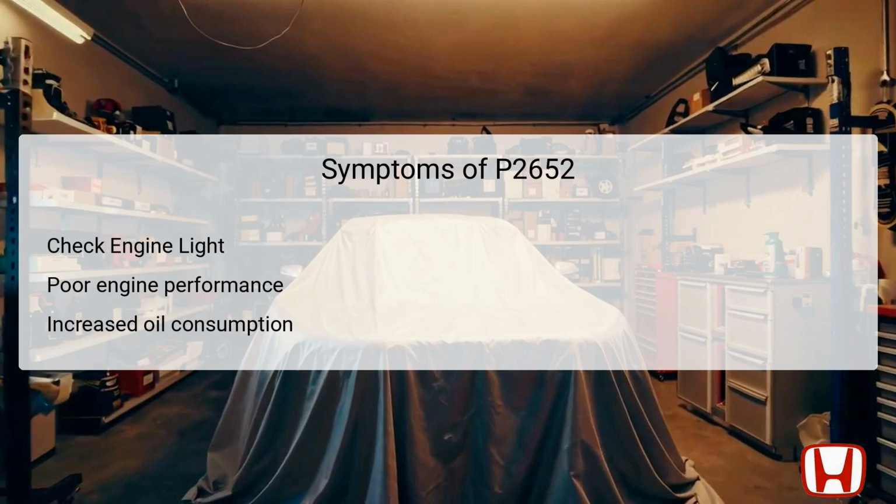Furthermore, abnormal engine noises, such as knocking or ticking, can occur as a result of insufficient oil supply to the rocker arms. These symptoms together highlight the need for immediate attention to avoid further engine complications.